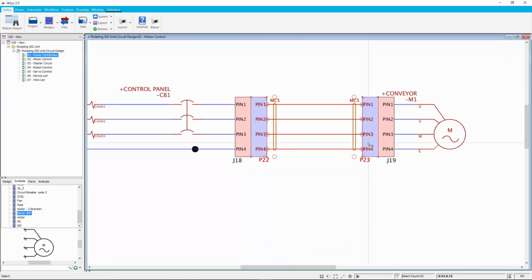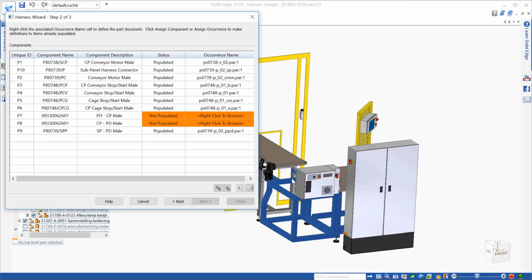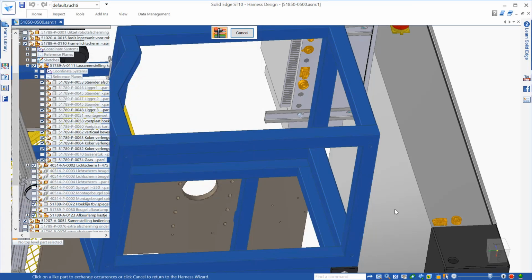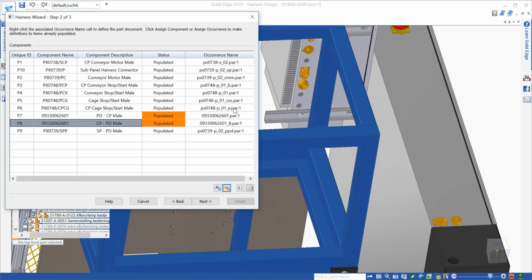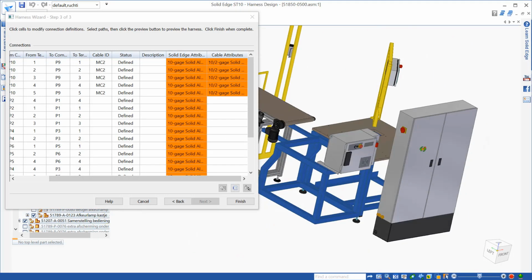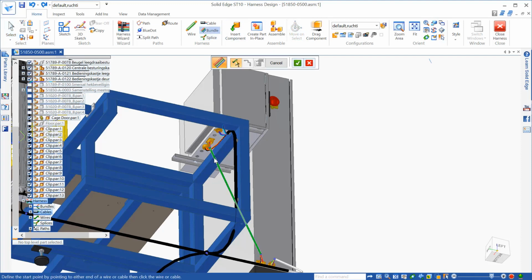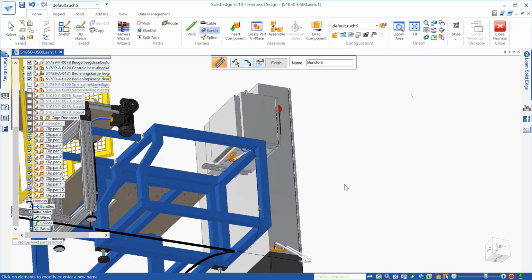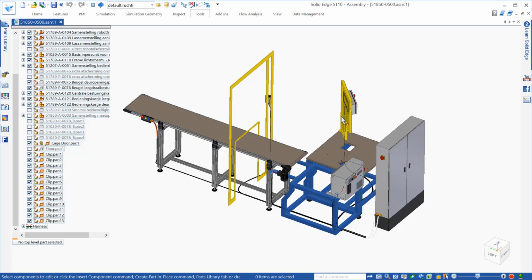The schematics can be exported for Solid Edge to read in and automate the placement of the wires in the correct pin locations. Once the wires and cables are in the assembly, Solid Edge's wire harness routing tools make an easy job of creating paths and bundling the appropriate runs together. Once the routes have been finalized, Solid Edge can then export all appropriate information back to VESIS with the final wire lengths correctly calculated.